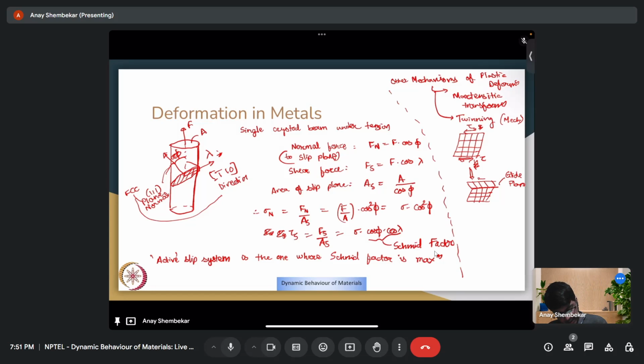And then this process can keep on repeating based on your applied load. The thing to notice here is that there is usually reflective symmetry about the glide plane, which is why twinning comes about. But usually these mechanisms compete with each other, say twinning and slip. You can think of it by looking at this crude, representational diagram: because the entire crystal structure has to be displaced above the glide plane, a lot more energy is needed.